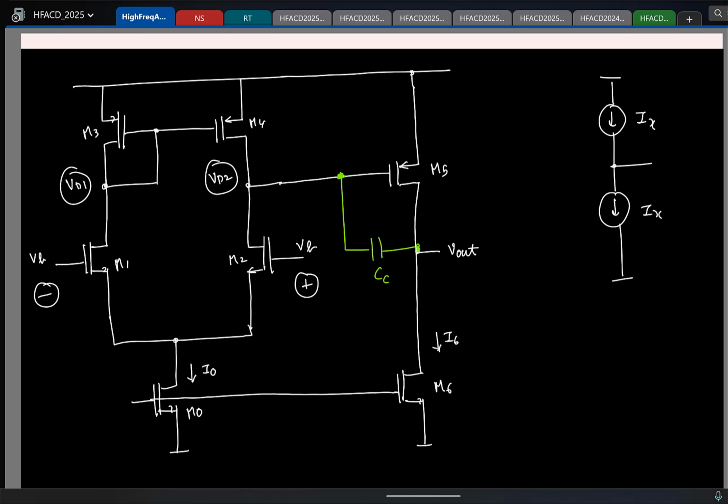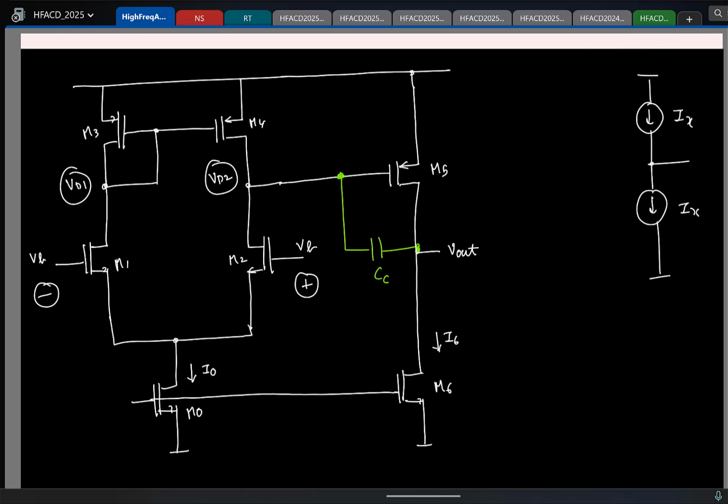And in practice, this is even more serious because I have an NMOS and a PMOS current source like this, right? And whatever I do, it is not practical for me to make sure the two currents are equal. So let us say I have a case where the NMOS current is greater than the PMOS current.